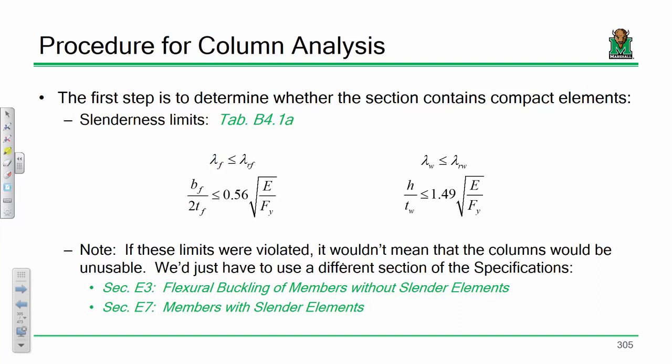So like I said, I am going to make you go through this analysis. Now, one thing to keep in mind, a local buckling analysis is really easy. All you need are two ratios. You need the flange slenderness and you need the web slenderness. Fortunately, if you look on your I-shapes, table 1-1, they're right there. See over here on the right where it says compact section criteria? They're right there. So you have the flange slenderness and the web slenderness already computed for you. You don't have to go out of your way to compute it.